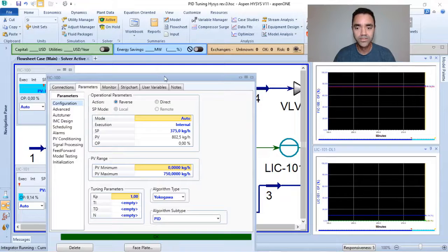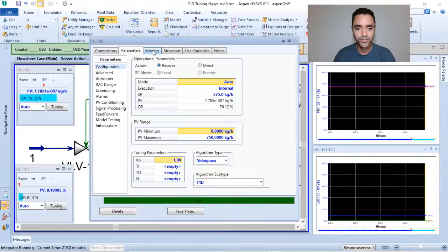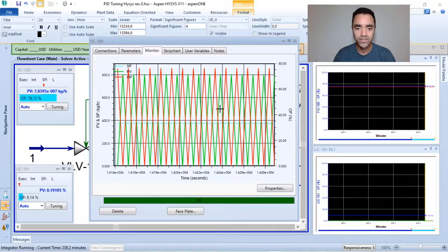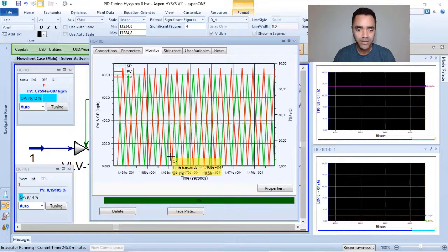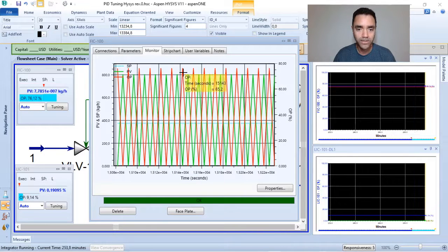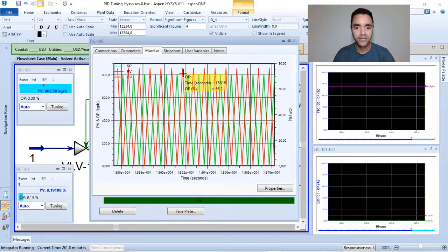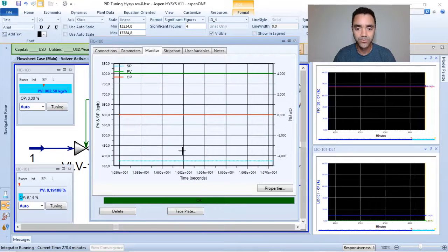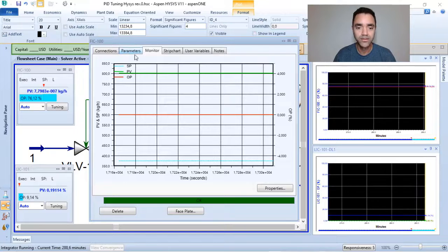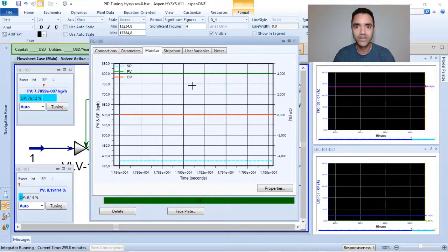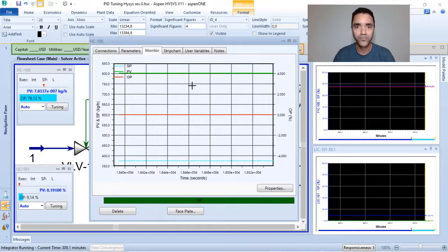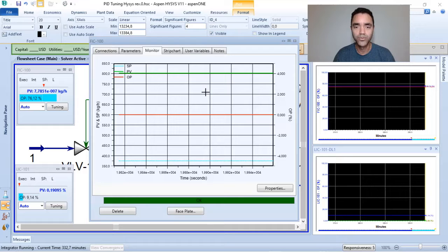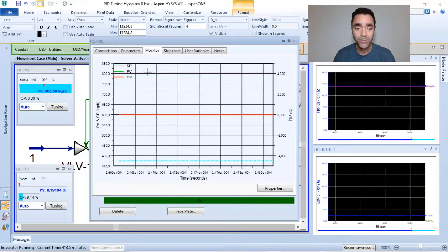So what I can do here to have a more stable condition for my process? First thing is that you can see that from one point to another, the opening of the control valve is too fast. It goes from 0 to 100%. And sometimes, most of the time, when we are dealing with the dynamics in Aspen HYSYS, you will have some kind of abnormality.